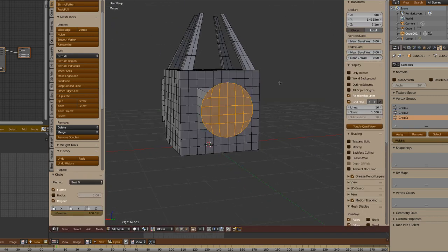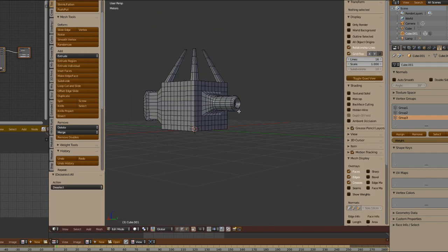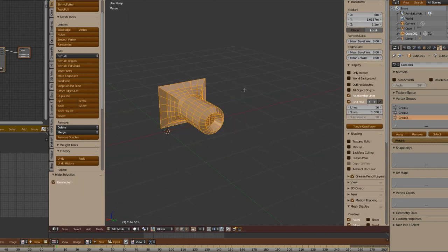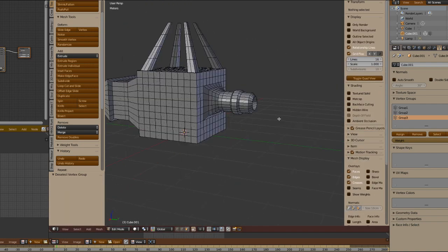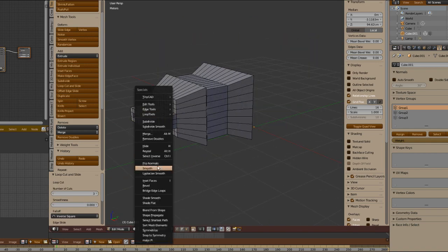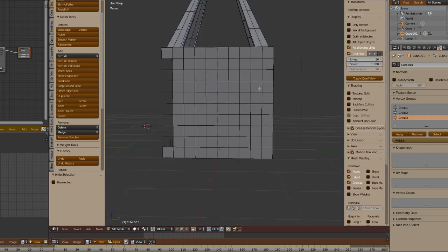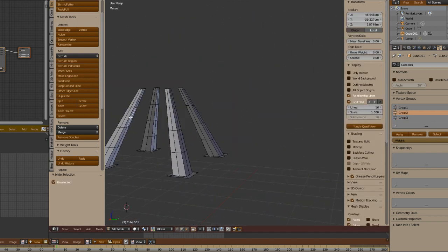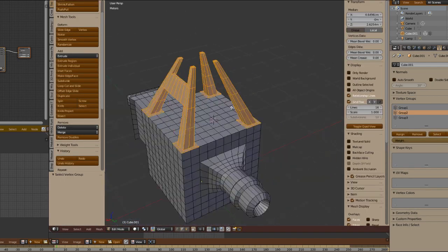With vertex groups, the user could create groups of polygons, vertices, and edges that would be used to influence a certain part of the mesh, would allow modeling, as well as a quick way of selecting and interacting with the mesh, allowing functions to hide and visualize parts of the mesh that the user would be working through shortcut keys, and also in the creation of masks or freezes.